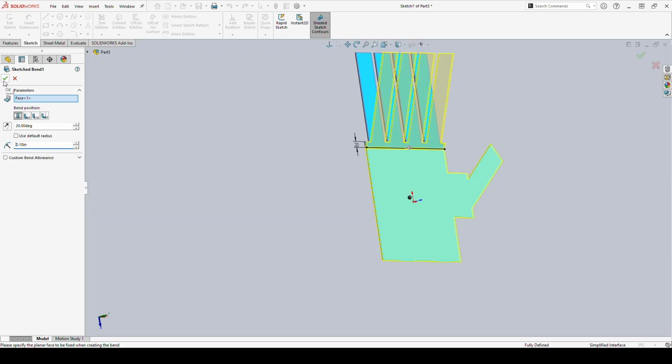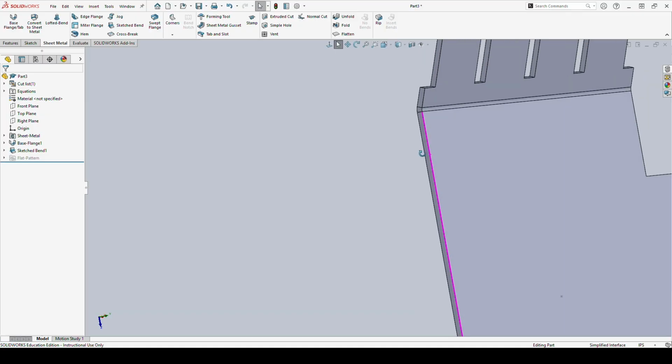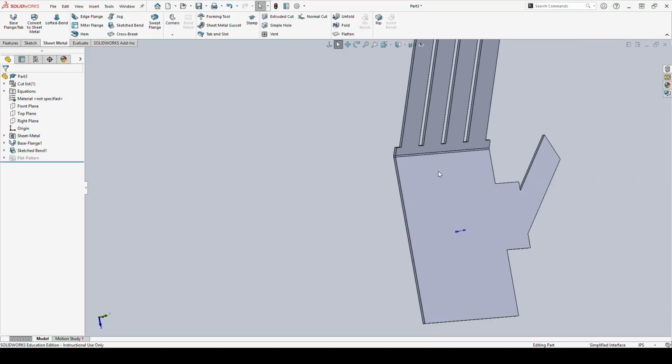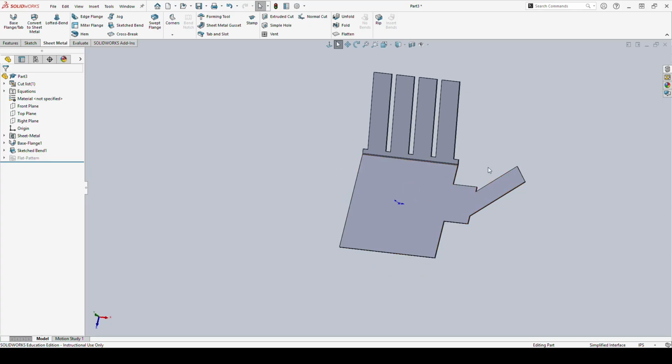And what that is physically doing is changing the radius of my part right here. If I chose a more drastic number, it would be a much bigger radius. And as I get closer and closer to 0, it becomes more of just a flat curve. So very small number, very small curve. Large number, large curve is just the radius of how the sheet metal is rotated here. And we'll show that a lot better in a little bit when we're talking about some other things.